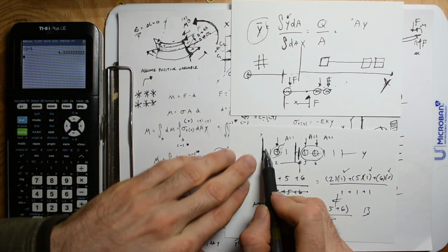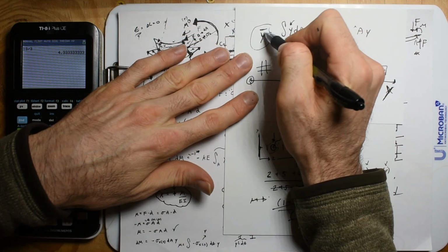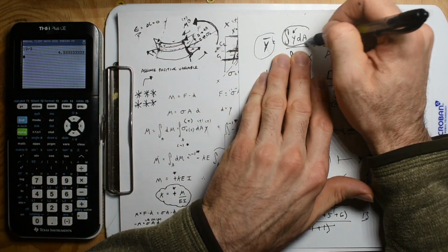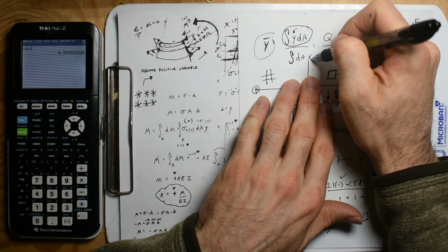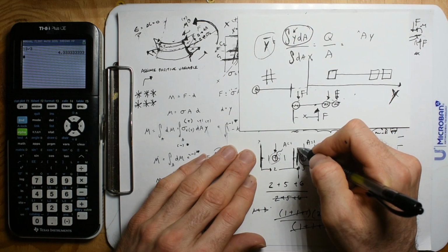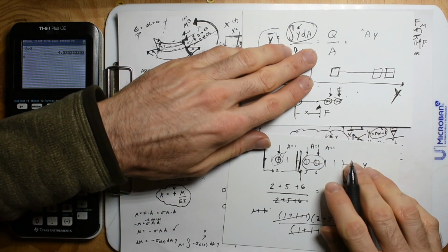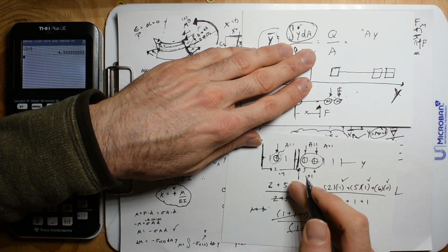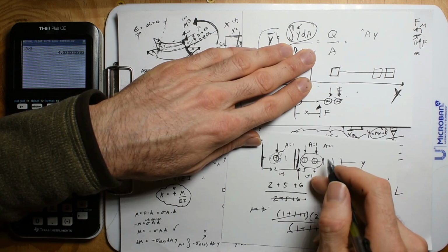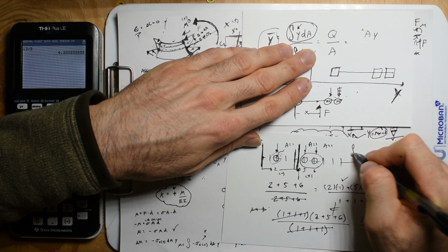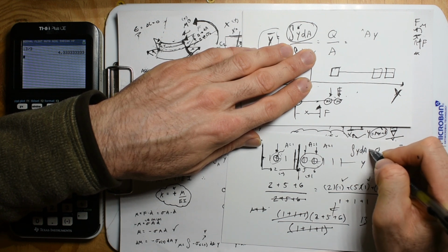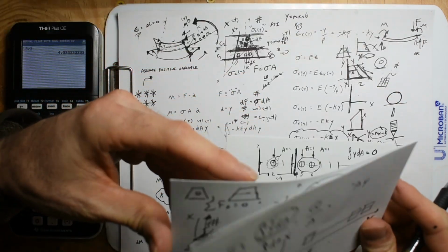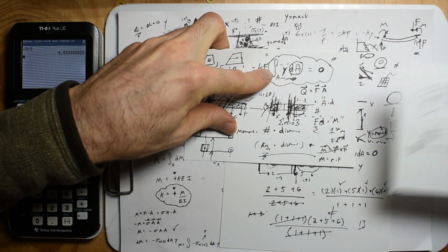And so what we did is this equation, we found the center by taking this moment. Yeah, this part is the moment of area. But then if you divide it by the area, you get that centroid. But if I now know the center and I want to just take this, I want to sum this area. This area is going to be a positive distance. This area is going to be a negative distance. And so those will sum to 0. So if I start at the centroid, this integration of y dA is equal to 0. I do need to spend more time on that, but that is the take home for that equation of like this part of the integration.